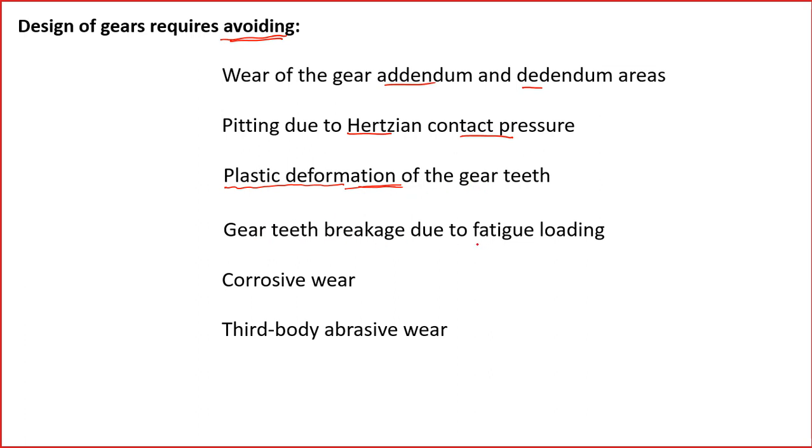Gear teeth breakage due to fatigue loading. So since the base of the gear tooth experiences both compression and tension load, that means there is a huge amount of stress variation, therefore it will lead to fatigue or bending and fracture. Then we should also avoid corrosive wear, because if the environment is not suitable, if there is humidity or some other chemicals, then the gears will corrode, and that will lead to failure.